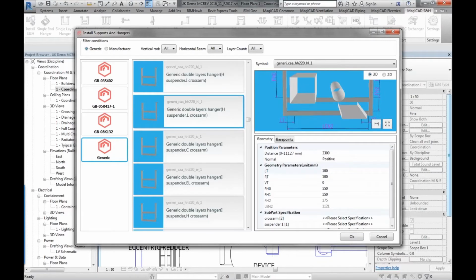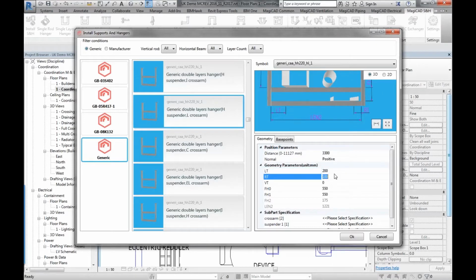You'll have these base points on this tab here. What it's doing is automatically reading the level of the underside of the slab, which it's determining by the locality of the nearby architectural structural elements. So this time it's found the slab. You can also change that to be user defined and start putting your own hosts in there if you want to, but I'm going to use the automatic one now.